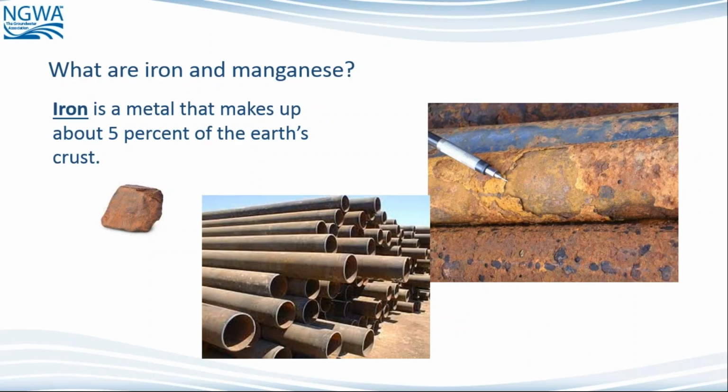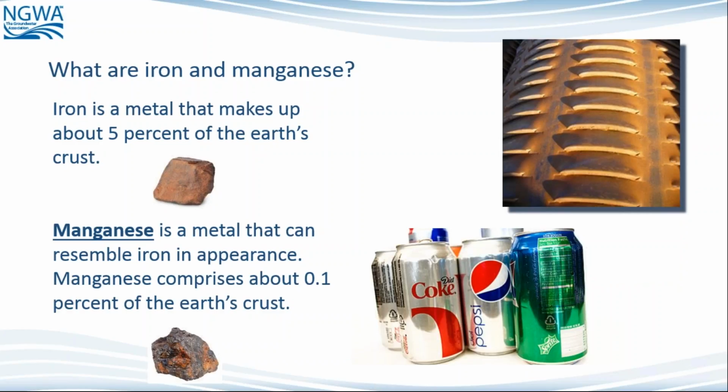However, the availability from the mining of iron means that we actually construct our water wells from it. Not all of them of steel, but a majority of them are made of a steel product, so we actually have the availability of iron solubilizing within the water well, along with the natural available iron from the geological formations in the subsurface. So iron's a big part of what we deal with in the groundwater industry.